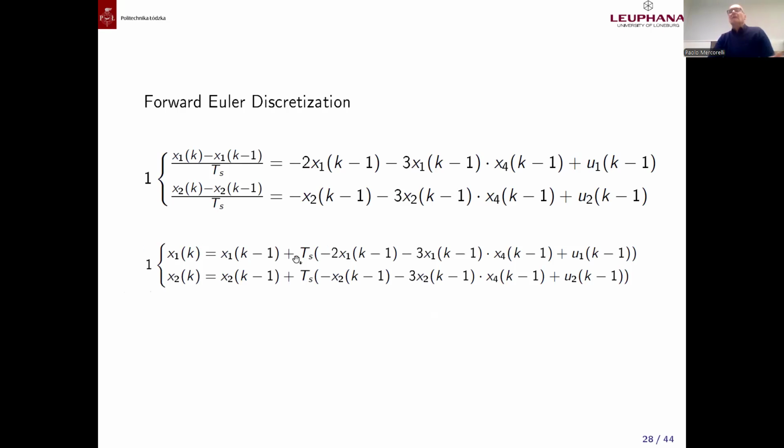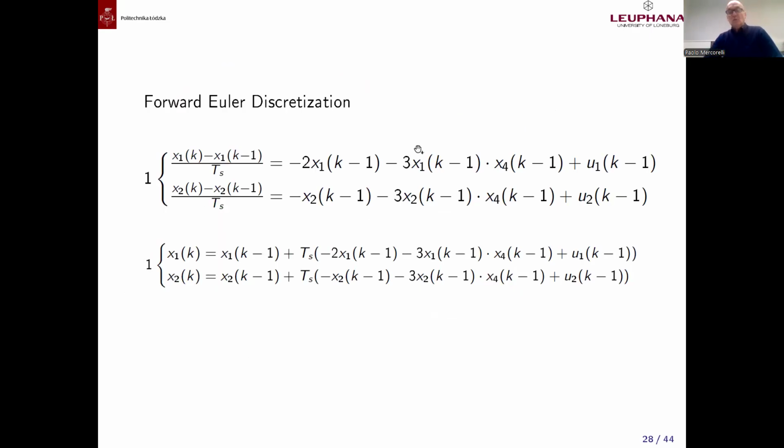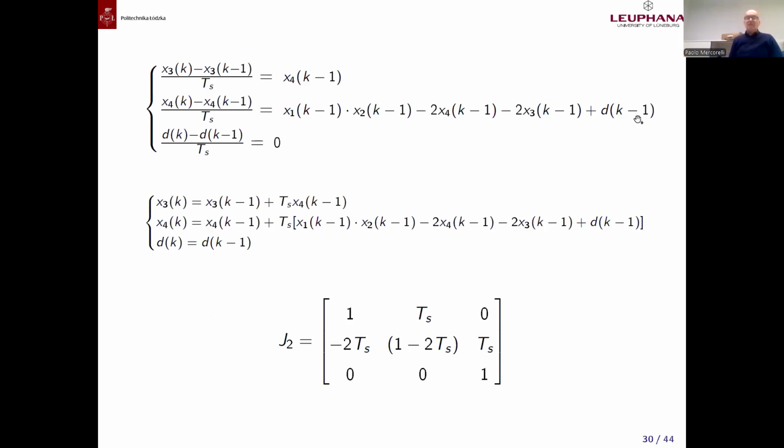It's the model. Yes. But think about that, including the Kalman filter, here it becomes hat minus. On the left, everything, this x1 and x2, becomes hat minus. On the right, everything, roughly speaking, hat must be added. And the Jacobian, in any case, is something included in the Kalman filter. I mean, this could be considered as the model. But the Jacobian, okay, I can write also in an abstract sense, but just to be more precise, at least in this representation.